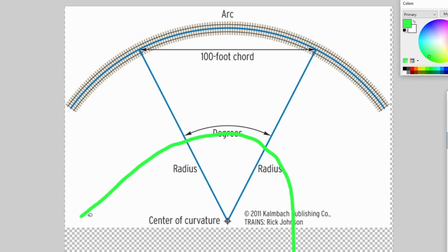And so you will have what is called tangent track running straight in this portion, and you'll have the point of spiral right here where the track begins to spiral. And then at some point you will have the spiral to circular curve point, or the SC point. So we spiral in, we're increasing our degree of curvature or reducing the radius as we get closer. And in this region here, we have a constant radius.